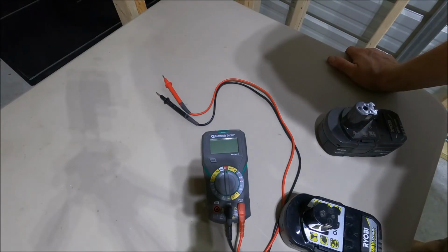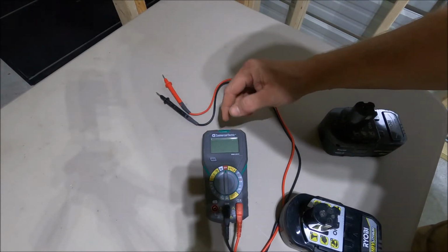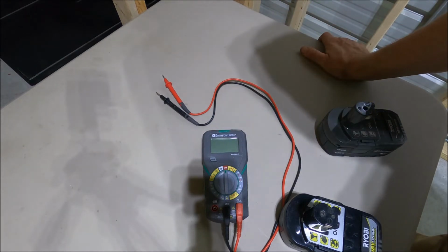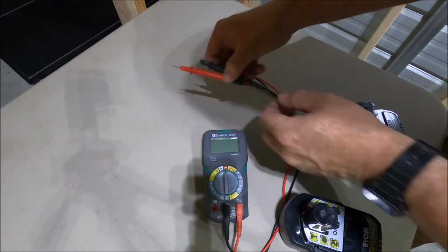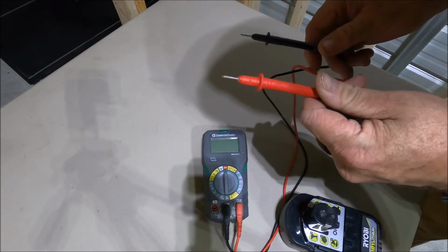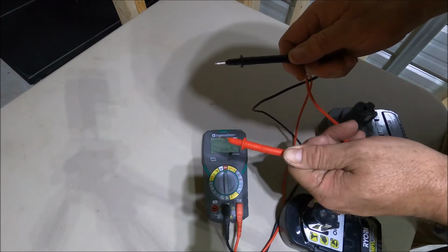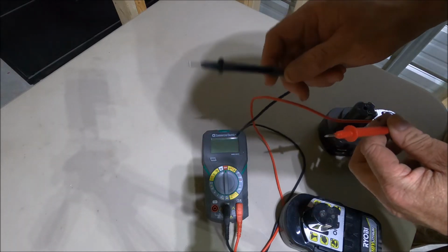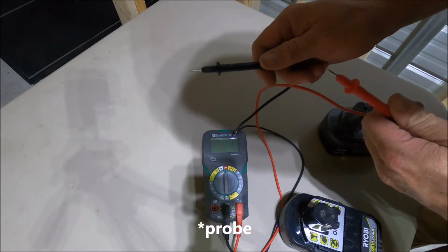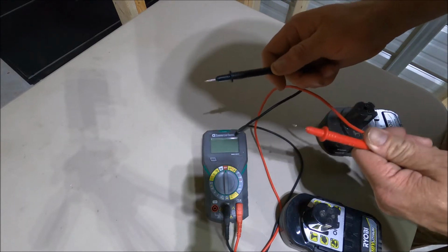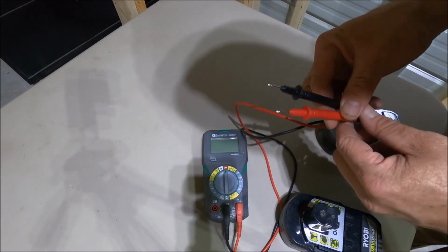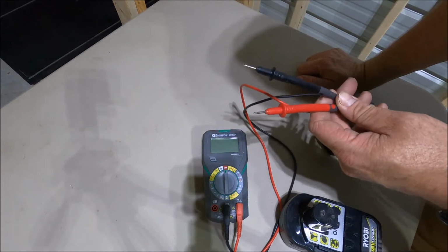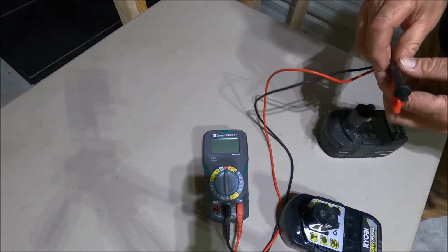So you've already seen me use the multimeter. I keep calling it a voltmeter. These are called multimeters. So you've already seen me use the multimeter with AC circuits in other videos, where I'll put the hot on the black wire on the gold screw and then put the black terminal on the white wire on the silver screw or in the outlet to make sure I'm reading 120 volts, make sure the voltage is correct. But there are applications for DC voltage.